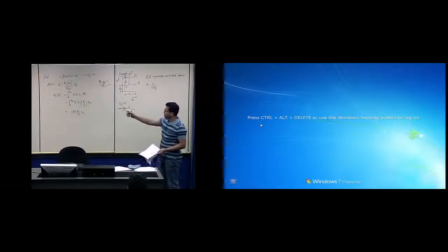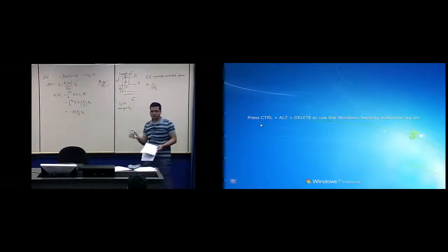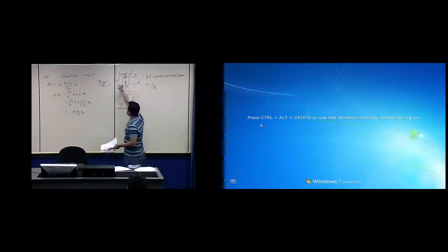We are using this condition at the free ends to equate it to 0, but now it's not a free edge, so we can use the reciprocity again, evaluate the value at this point on this segment using the shear flow equation we developed there and equate it to that. So that will be our boundary condition in this case.